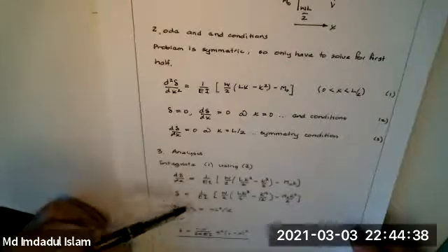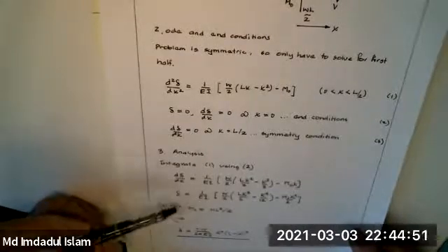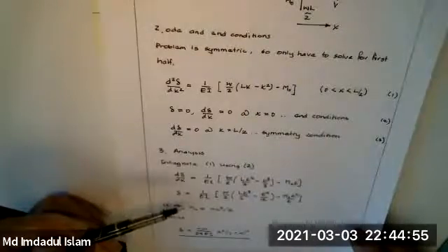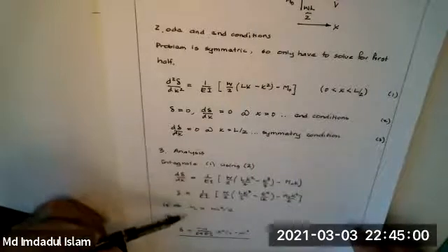The difference is here when you approach it by doing integration and not using superposition, it's not until the end that you get what the unknown moment is. So superposition will get you statically indeterminate reactions relatively quickly. That's where it's really great. For actually getting the total displacement and solving the whole problem, if that's what you want, it adds a little bit, okay? But not much. But it gets this answer in about 2 lines, okay?